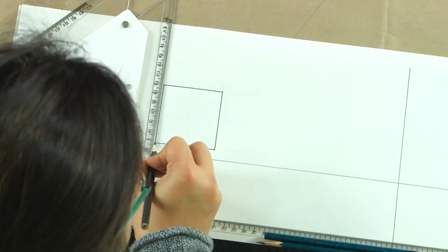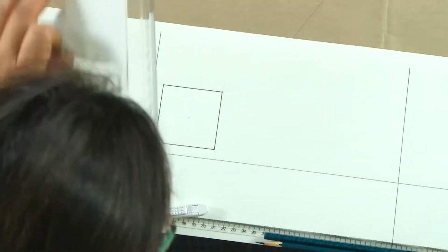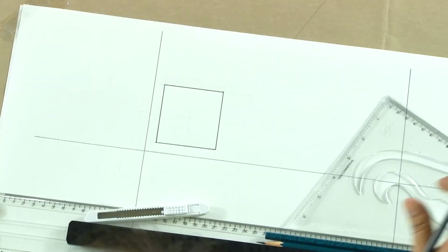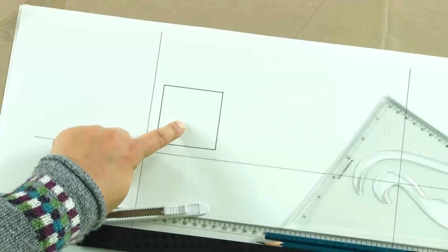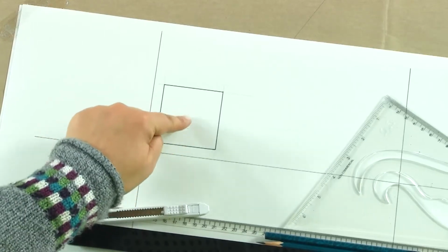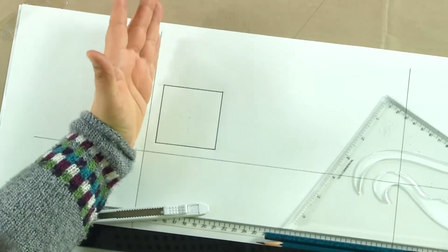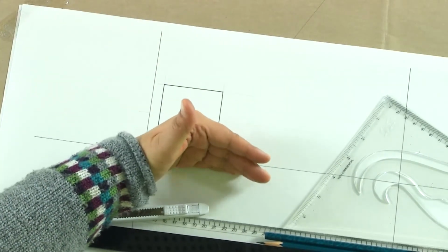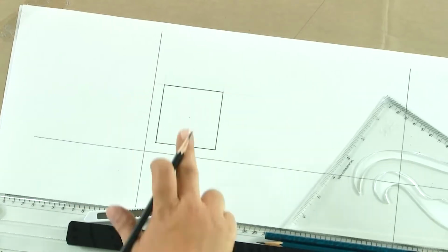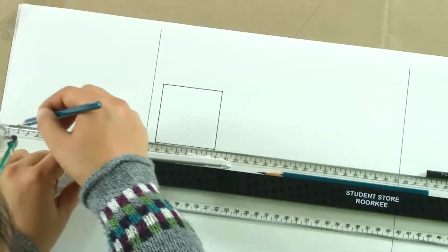Till now we were looking at lines, so there was just one line, but when we start with planes, we will have multiple lines representing one single plane. So, this is the square plane in question. It is 6 centimeter side, and its center is at 4 centimeter from both the reference planes. This is the representation of the vertical plane, and this is the representation of the horizontal plane for this side plane. This is what we have already made, and now we will draw the projections onto the VP and HP.